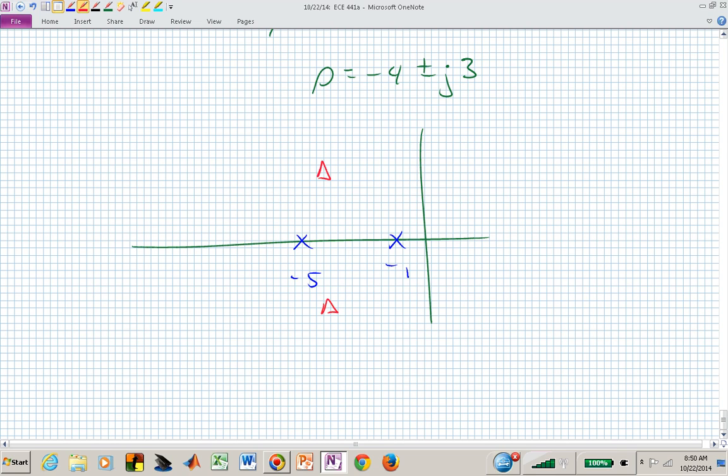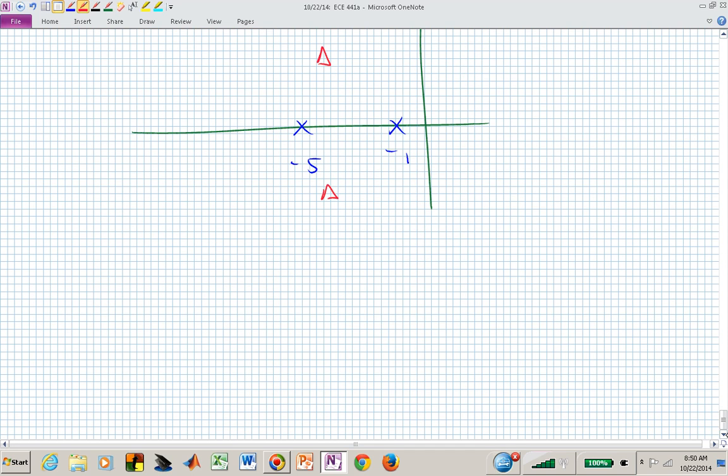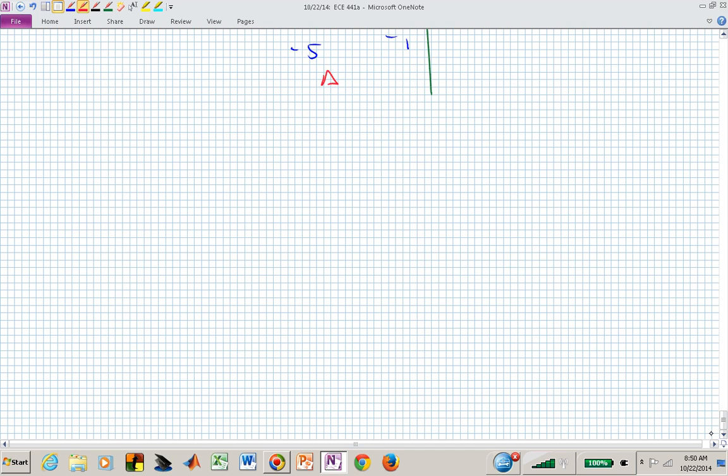We are going to figure out how to sketch this root locus. It's actually going to be something sort of neat. The eventual root locus, if we now had a pole there and a pole there and we had our 0 there, this guy's going to go that way, this guy's going to go this way. We've learned that they meet, then they start going this way, and they've moved a little to the left.